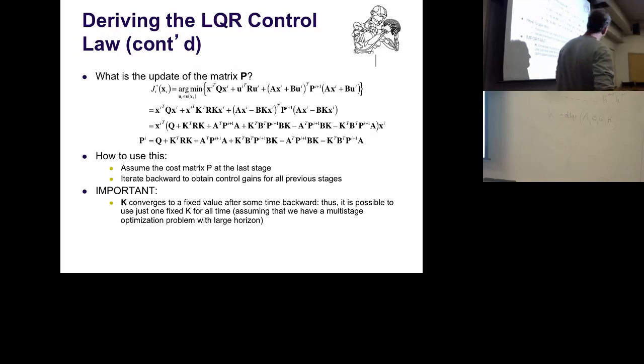Now, some people do adaptive controllers, learning controllers, where potentially the A changes, or you do a nonlinear optimization problem where the A changes over time. Since you don't know exactly which state you're in, if you're in a nonlinear system, you make a step forward, then you have to linearize at that new state, and you have to recompute the gain matrix K for that moment. So then you have to iterate. It's very easy. It's very fast. On a modern computer, that's literally microseconds. There's no issue to iterate these things. It's a very nice, robust control method. It gives you gains, and you don't have to worry about twiddling gains yourself anymore.